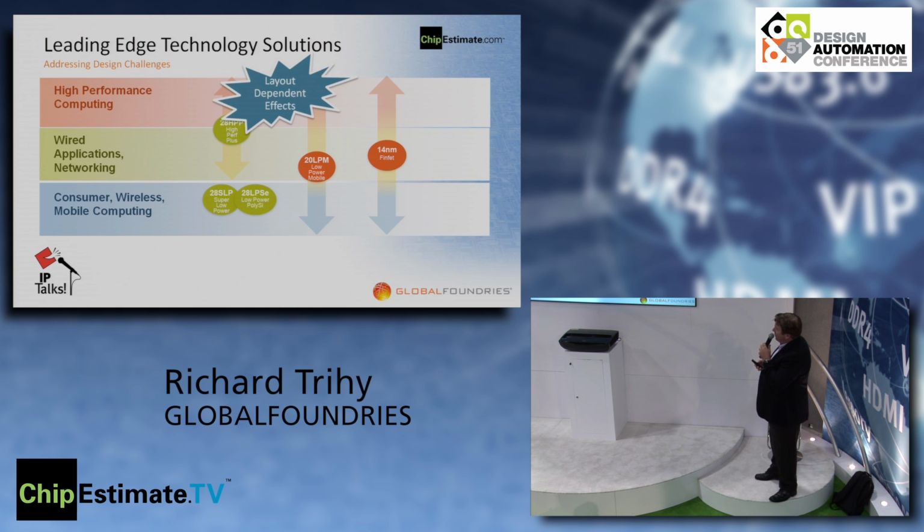Okay, so the purpose of this talk is to explain, from the design community's perspective, what challenges you're going to encounter as you go to design in these advanced nodes. So at 28 nanometer, we see a lot of layout-dependent effects. The best way to describe this is that when you draw the transistor, the behavior of the transistor is not just a function of that particular layout. It's also a function of what's in the periphery. And we need a way to model that and plan for that in the design.